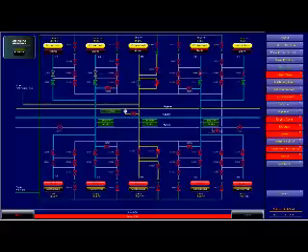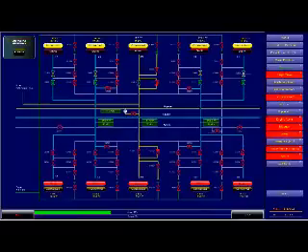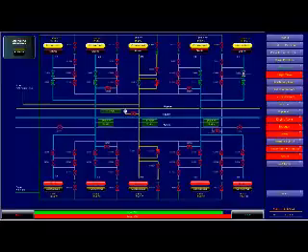Yes, sir. 129 degrees. Do it slowly because their line was not so cool. We always try not to give thermal shock to the system. This is our main objective of this training. This is a simulator, so you are not damaging anything physically, but on a vessel, you could damage your own bunker barge, your vessel, or the other vessel. Everything starts in a very slow process. Okay, so now we are happy.